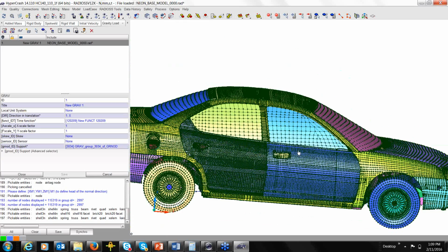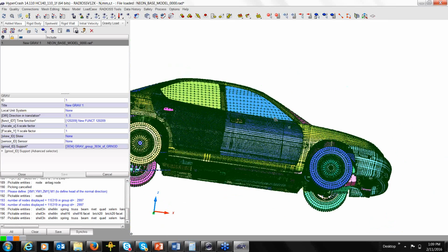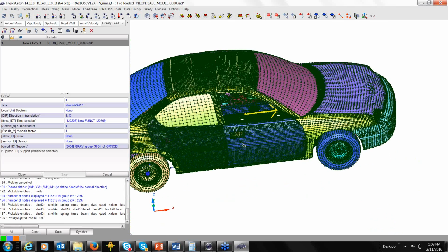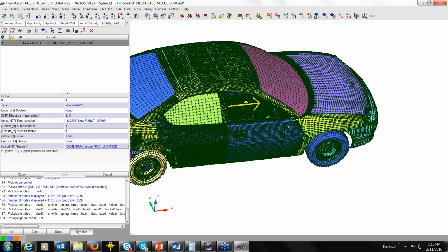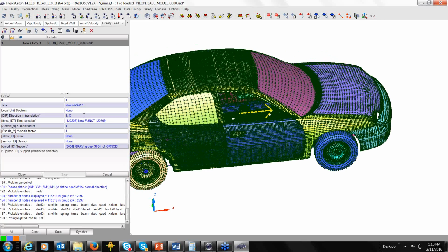In this model, it's a simple one for structural integrity only. We don't have the occupant, but later on you can have an occupant in this. You see the mistake I made here, right? I added gravity, but what is the direction of my gravity? So we make those mistakes sometimes. I need to switch that gravity. It's under this G, right? It's going down to the ground. So I change it, and then my direction will change. But it needs to be negative.